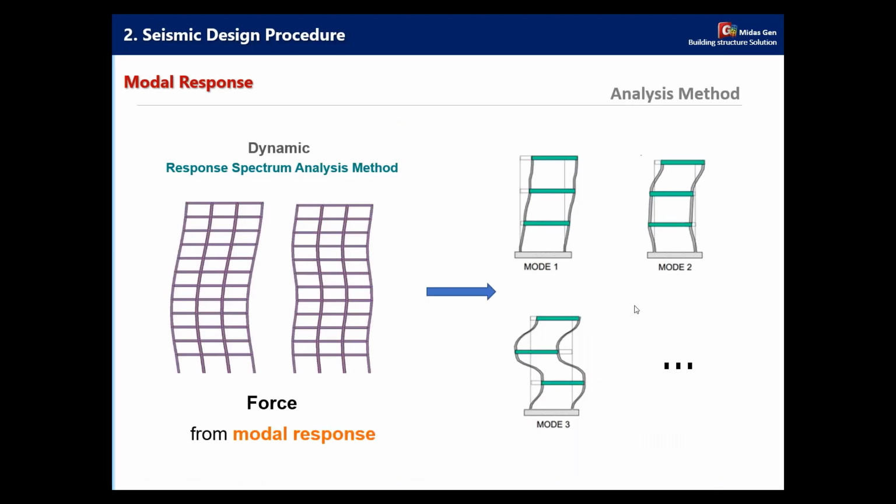These pictures show how we calculate the base shear according to each mode in the figure. When we have mode 1, the software will calculate the base shear accordingly. When you choose even 10 modes, or 10 frequencies of the shape, you can perform the analysis using eigenvalue analysis, and then you have the seismic force you are looking for.